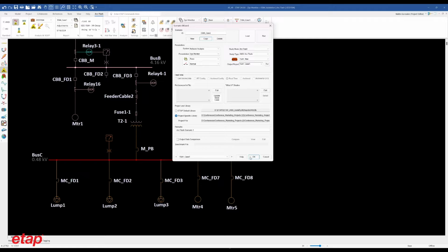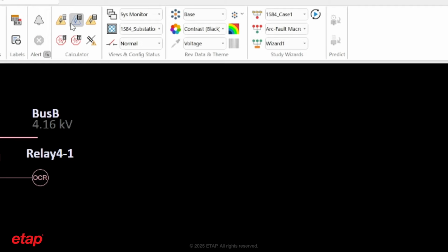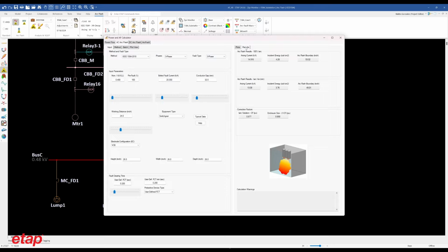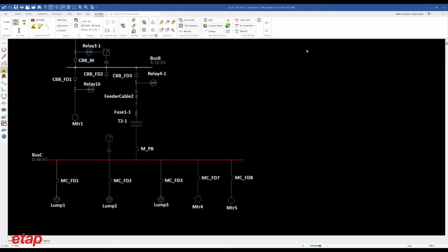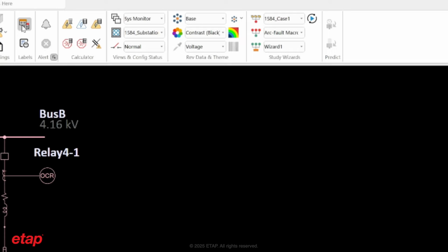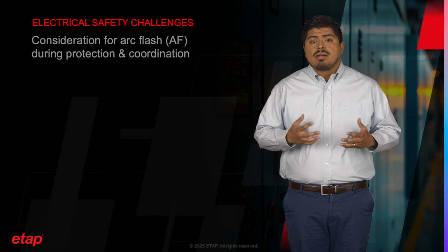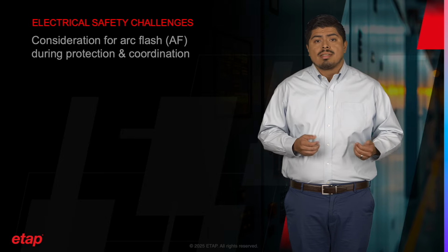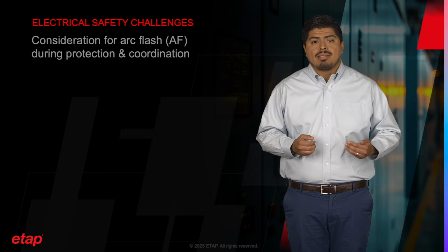Using the built-in troubleshooting tools such as the arc flash result analyzer, arc flash calculators, and time current curves, we can easily identify fault locations with high incident energy exposure estimates. This streamlines the process of determining incident energy mitigation recommendations for arc flash studies. Once you're satisfied with the evaluation, the ribbon bar also provides easy access for standard and custom arc flash warning labels. Now that you have a better understanding of how to use the new Power Ribbon, let's explore the unique tools ETAP has to offer.